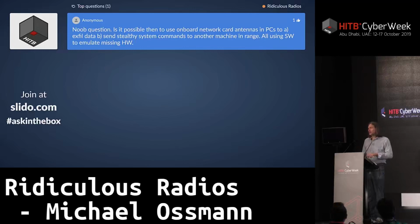An example of that, I would say, is how we were able to take this off-the-shelf Bluetooth device and get it into a test mode by telling its firmware to generate a test signal instead of generating a Bluetooth packet. And so that's an example of how we could implement just an on-off keying transmitter using this Bluetooth device that could be embedded inside a PC. And we would be transmitting on-off key data in the 2.4 gigahertz band that would not be detected by a Bluetooth sniffer, for example, because it's not a Bluetooth modulation.